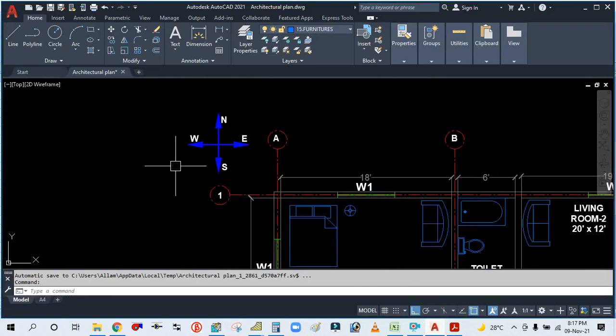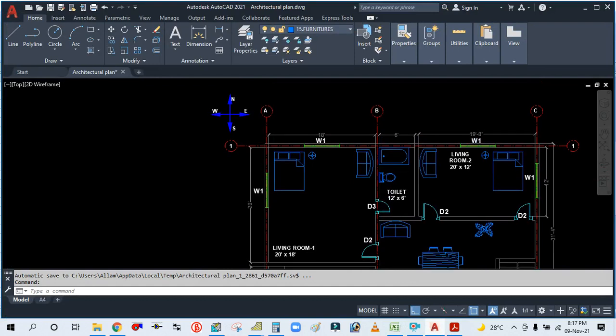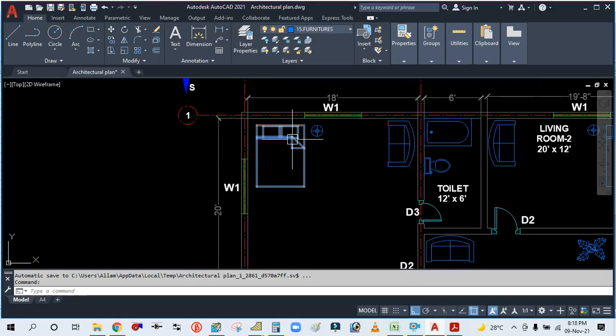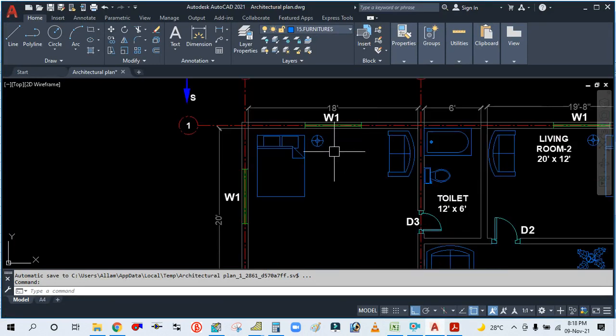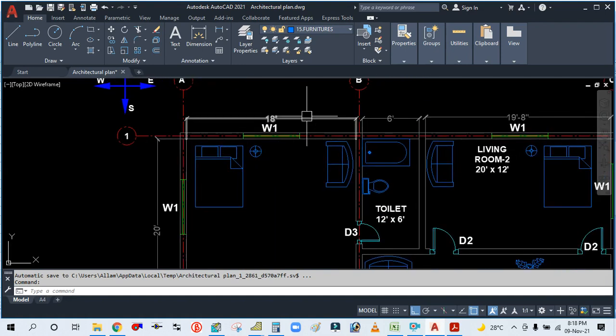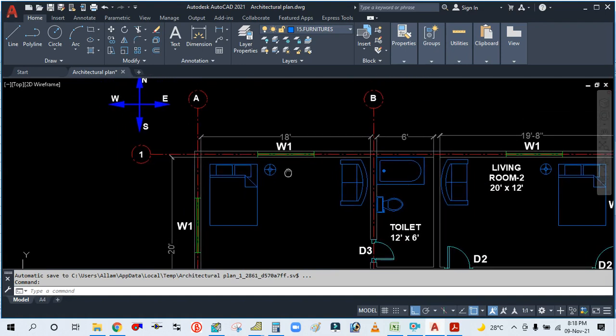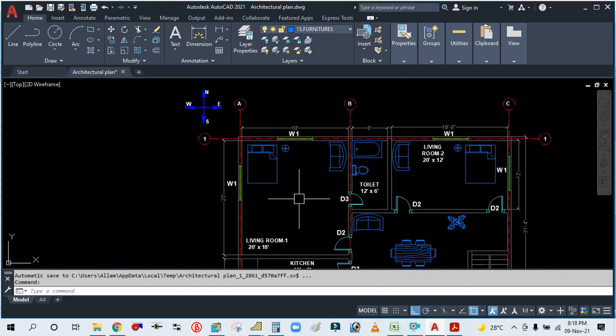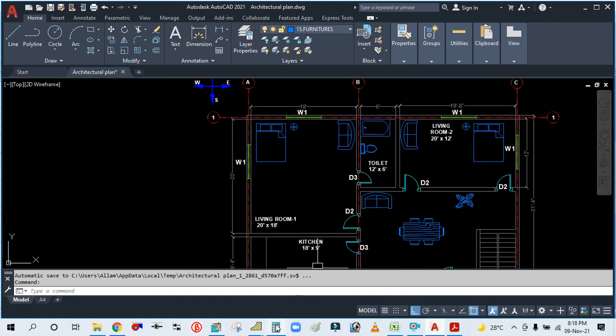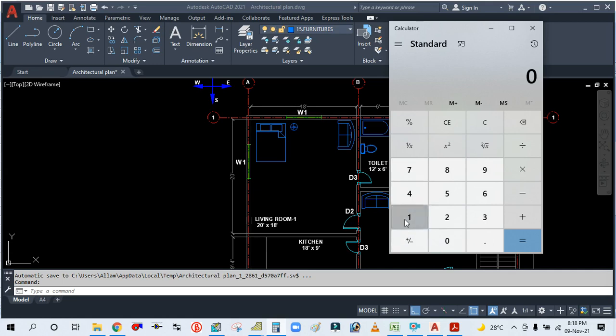Exposure is north and west for this space. For the north wall, generally in the E20 we are providing the net wall area, not the gross wall area. So the net wall area is 18 by 13, 18 by 13 height. The total is 234, minus 24 for the window area. Just subtract, and you get the net area of this exposure wall, 210.